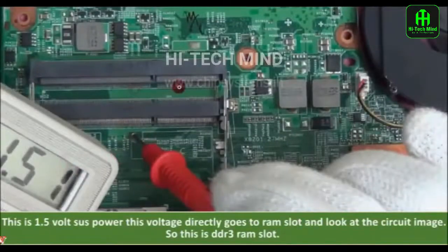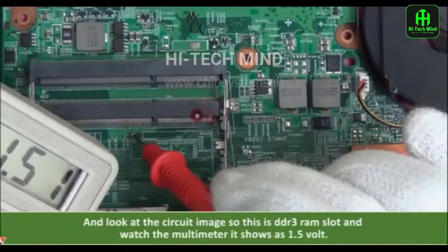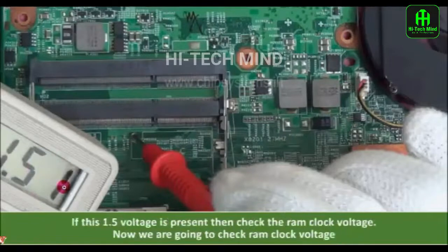Look at the circuit image. So this is the DDR3 RAM slot. And watch the multimeter. It shows the reading 1.5 volt. If this 1.5 voltage is present, then check the RAM clock voltage.